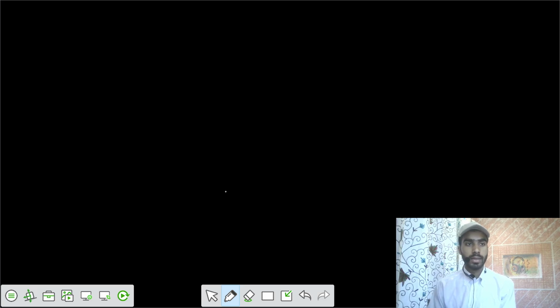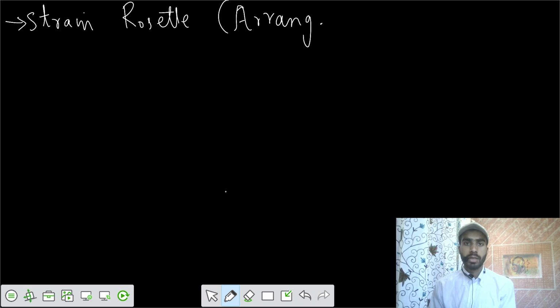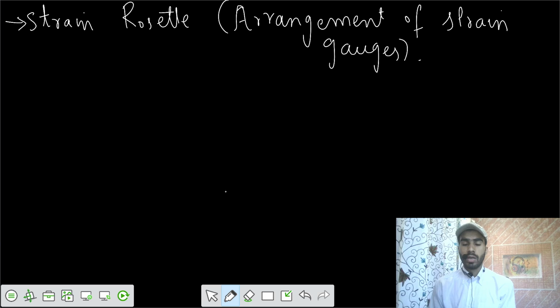Today's lecture is about strain rosettes, or the arrangement of strain gauges. In actual practice, shear deformations are difficult to find, so let's calculate only the linear displacements. We use strain gauges, which measure linear strain, or we can say normal strain.